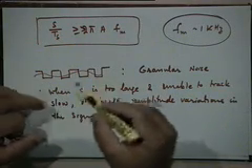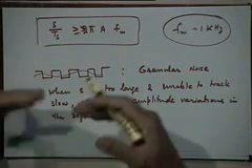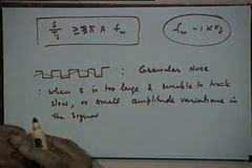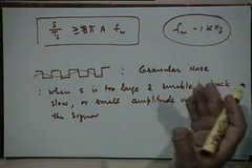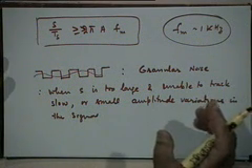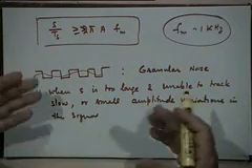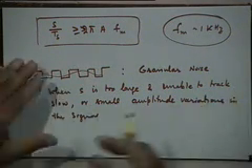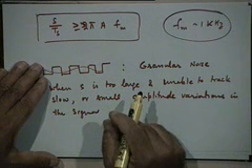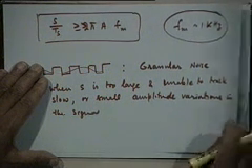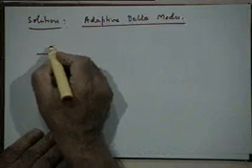On the other hand, if we face this situation, we will always get a positive impulse followed by a negative impulse followed by a positive impulse. Alternate impulses will be positive and negative. So, if you get a continuous stream of positive and negative impulses alternating, that is a symptom of the granular noise condition. So, we can monitor these two conditions by the nature of the output of the delta modulator and immediately try to take some corrective action, and that is the principle of the adaptive delta modulator. If you keep that in mind and then look at this picture, it will start to make sense.